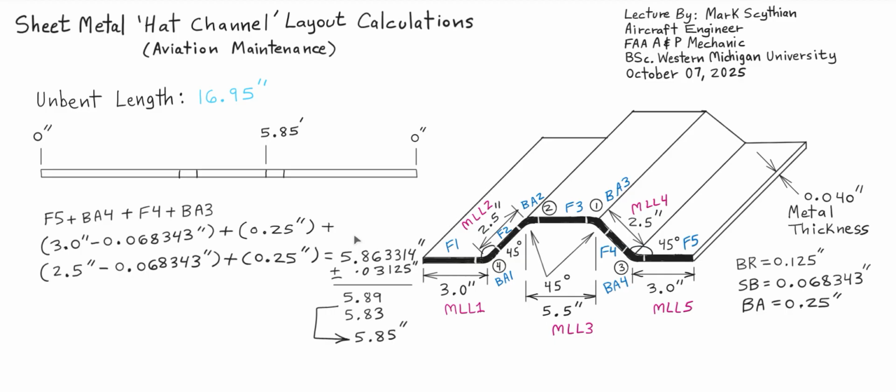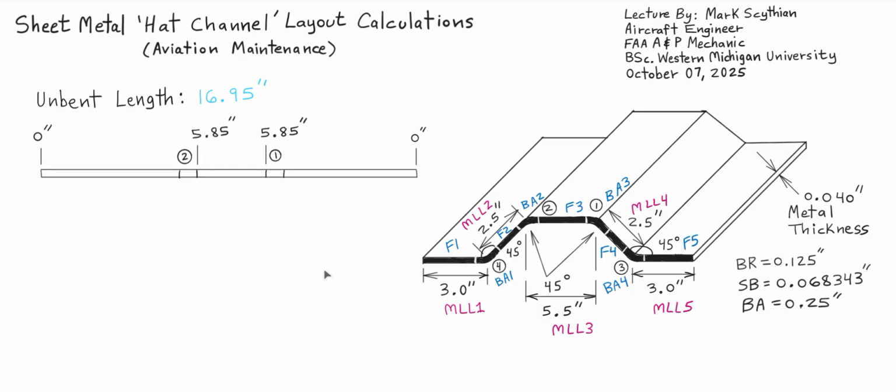So start by placing the first bend, and this section here will turn into the bend allowance, a controlled bend set at 45 degrees. So you go ahead and move it to 45, it might spring back 1 or 2 degrees, and then you might move it up to 46 and 47, and then you have your nice 45 degree bend. And then you repeat the process on the other side as well because it's symmetrical, but you must bend these two first, so first and then second.